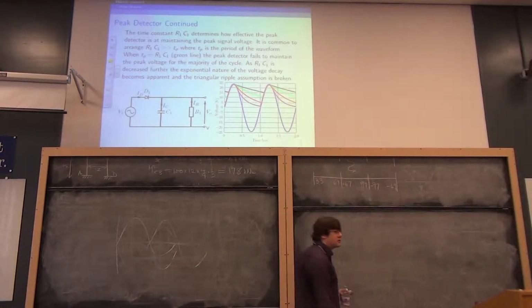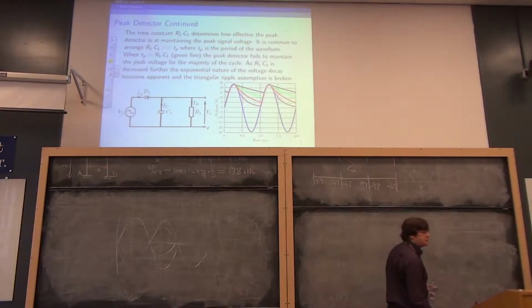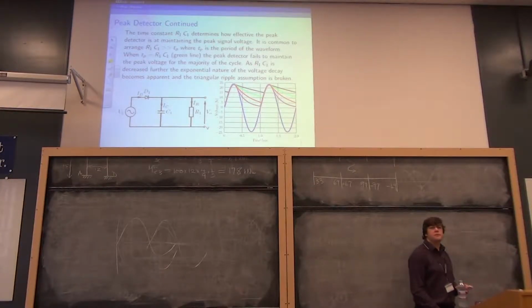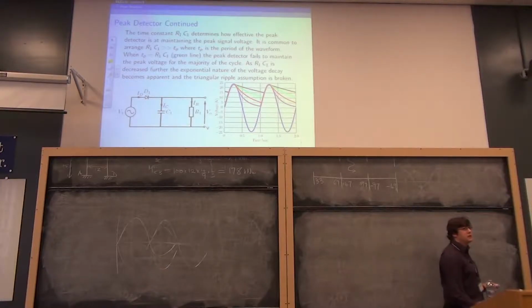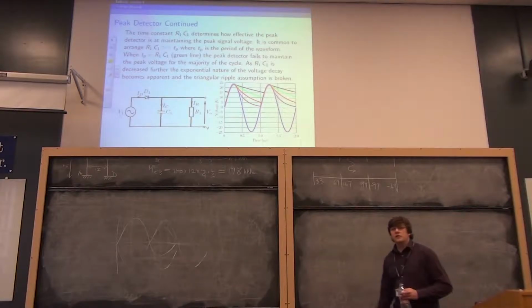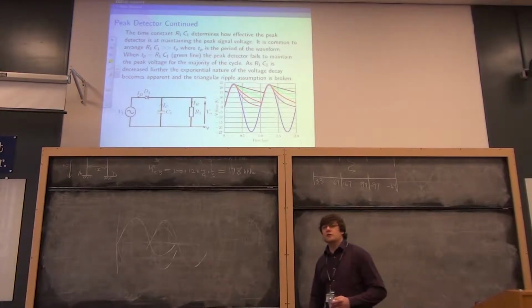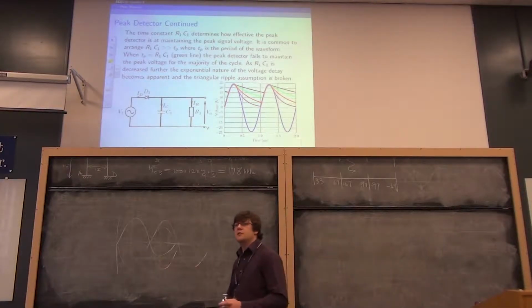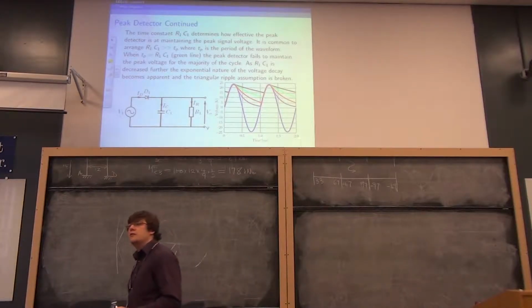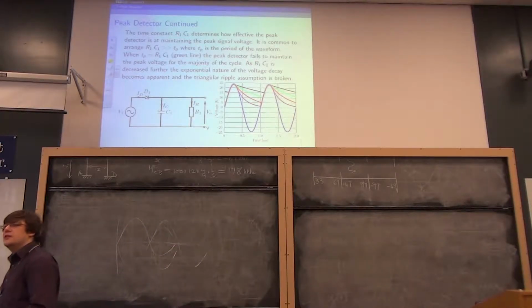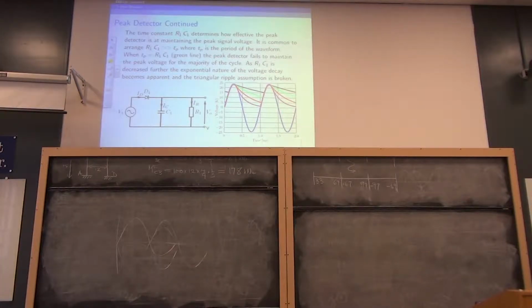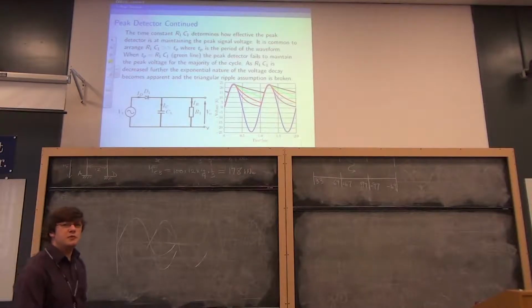And afford is not necessarily a case of money, although it often is a case of money. It's also a case of space, and also perhaps a case that some capacitors will only work at 85 degrees C for a certain number of hours, and others will work at 105 degrees C. And if you've got a very small volume, which is already quite hot, and you fill it with a large capacitor, you might find the airflow around that component is something awful, and making it just a little bit bigger means you need a 105 degree component instead of an 85 degree component. And the trouble with the 105 degree component is they're much more expensive.